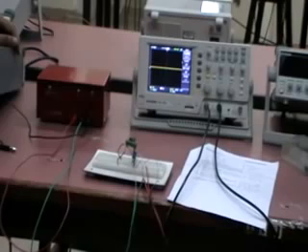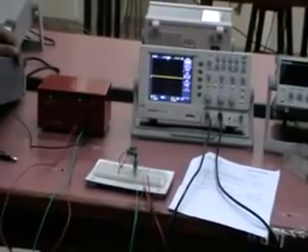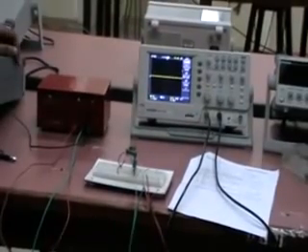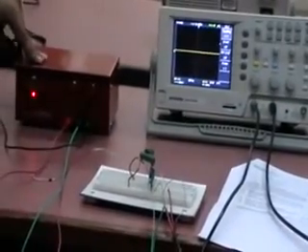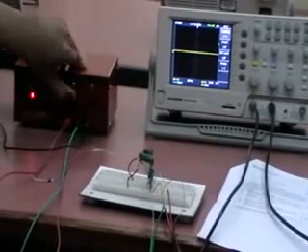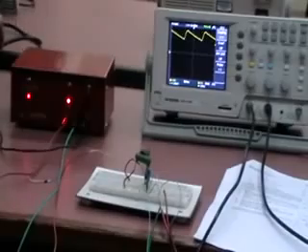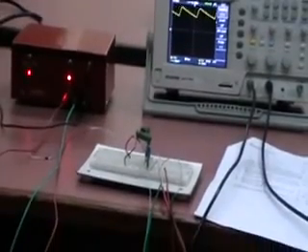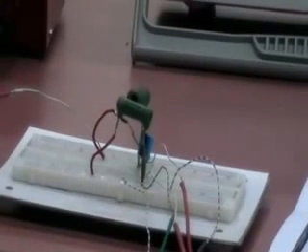So, coming to the rectifier part with capacitive filter, in this section we will study the effect of capacitive filters on ripple voltage and peak diode current. The 1 ohm resistor in the following circuits is used to observe the diode current waveforms, by using one channel of the DSO to observe the output voltage and the other channel to observe the diode current simultaneously. We have two channels, channel 1 and channel 2. The circuit connection is done according to the diagram that is given in the manual.